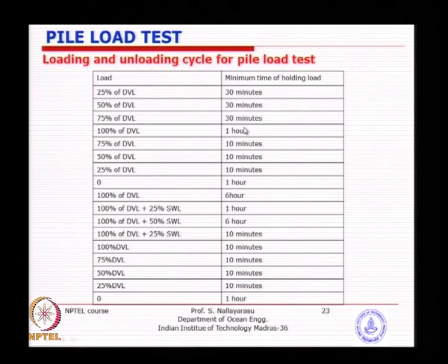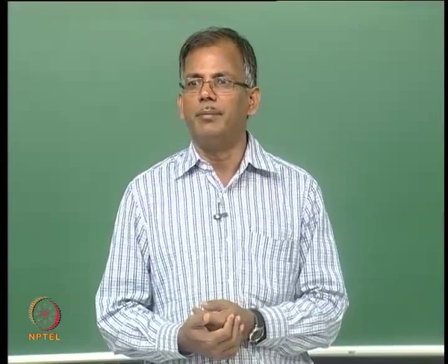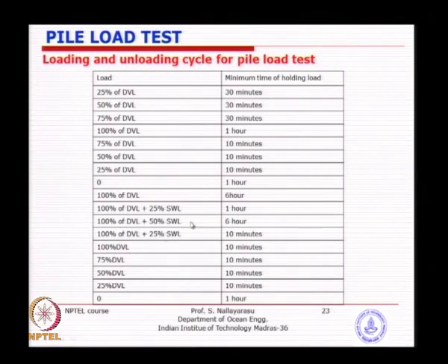a little longer time, and then during the unloading process, because relieving of elastic compression will happen just like this, it is not going to take time. So, for unloading they are just allowing only a little time, 10 minutes, and then again restart the process 0, 100%, and you are going to do an overloading test. There you are going to wait a little longer time beyond the design verification load, if it is a working load test, and then repeat the procedure.